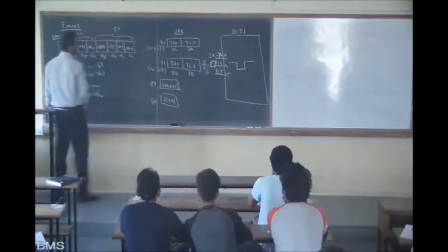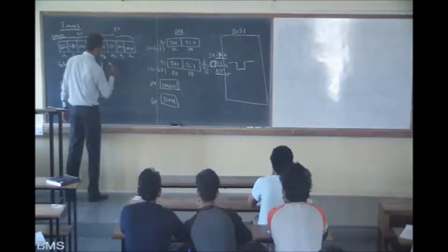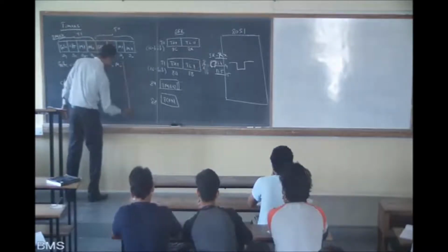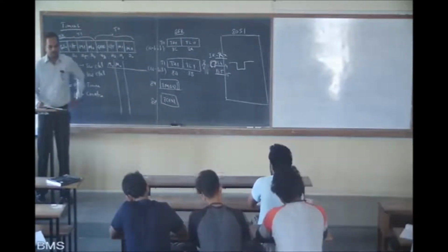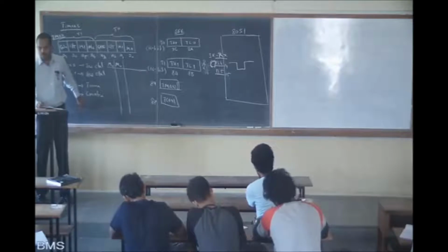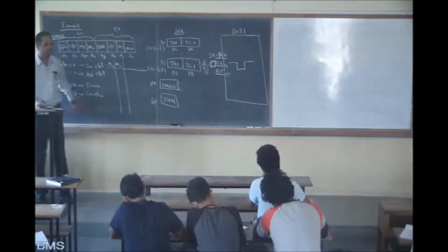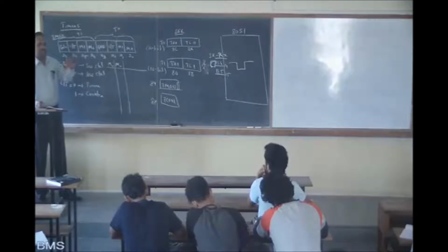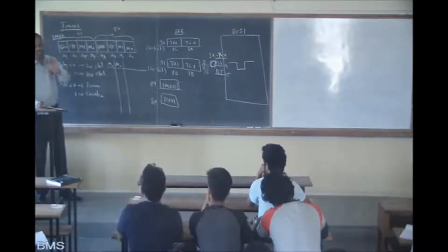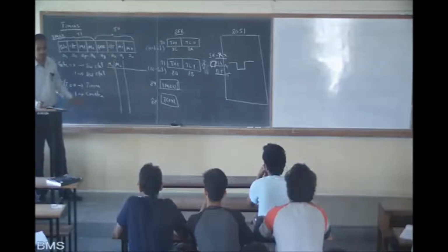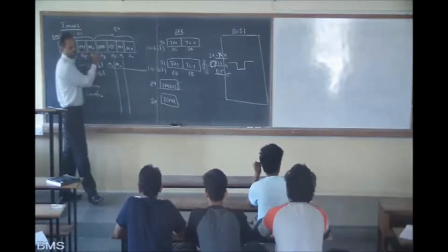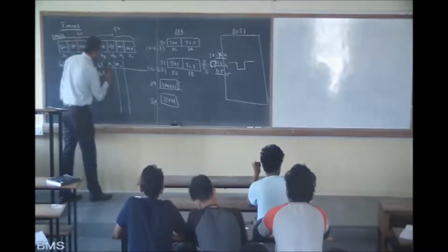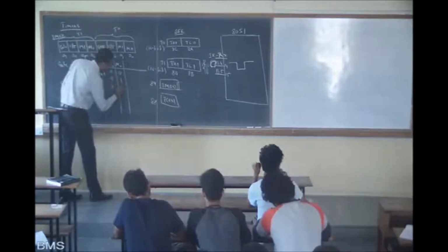Right. Next one, M1 and M0. Any doubt in this? Timer, counter, clear, right? You can think like this: external interfacing, counter; internal, timer. You have to set it. That is very important. Now M1 and M0 are mode setting bits. They can be 0 0, 0 1, 1 0, 1 1.